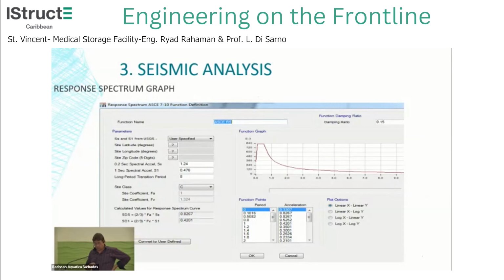Right. So what's our earthquake we're designing for? We're designing for an SS of 1.24. That's our short period spectral acceleration. This is what we put in the computer. You can see a rigid building, one with shear walls or bracing, is going to experience the most from the earthquake in terms of spectral forces on the building, which is bad, structure and contents-wise.